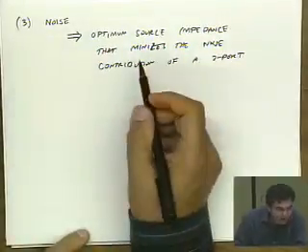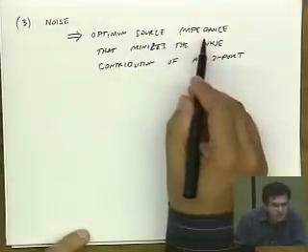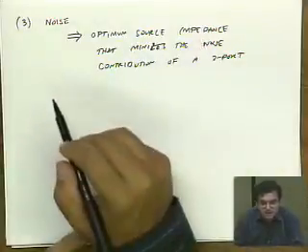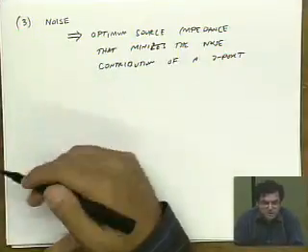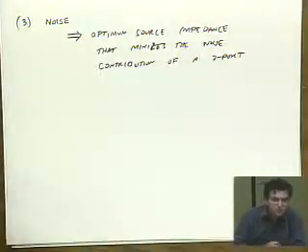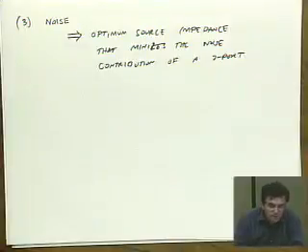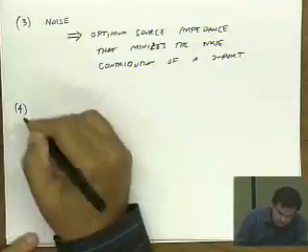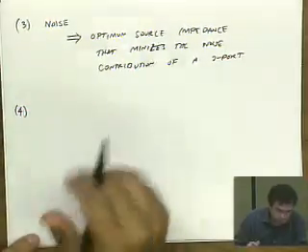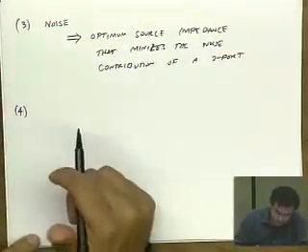And in fact, this optimum impedance is not necessarily the same as the optimal impedance for maximum power gain. So in some cases you have to make a compromise and ask yourself, do I want to match for gain or do I want to match for noise? And so that's another reason that we would impedance match. And we'll go into this in a lot of detail later in the course.